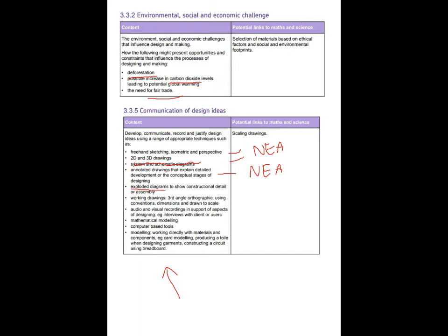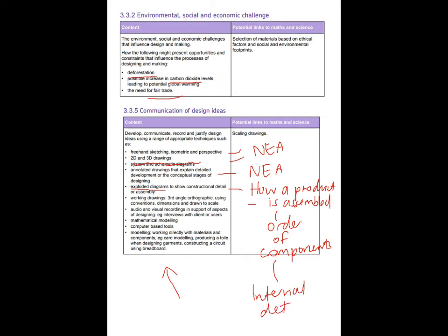Exploded diagrams, useful to show how a product is assembled. You might want to just give a quick Google to exploded drawings just to give you an idea of what they look like. Exploded drawings basically show how a product is assembled. It shows the order of components, and it can be useful to show internal details.